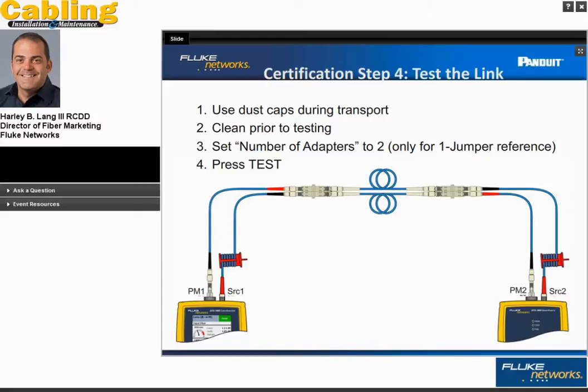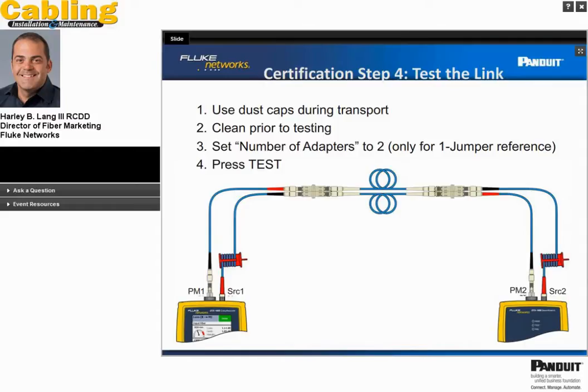In fact, dust caps can actually add contaminants to the end faces of the fiber. So always use the caps to protect the end faces, but always clean after they've been removed, before they go into a piece of test gear or into a connector adapter.